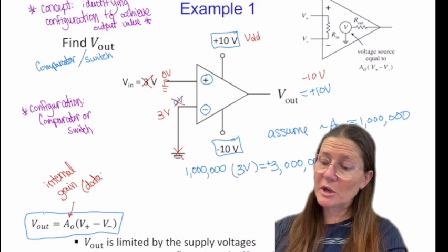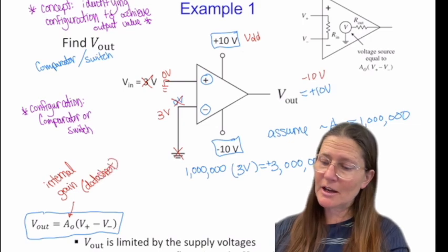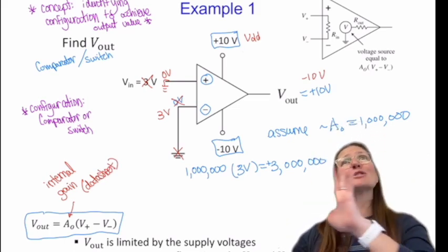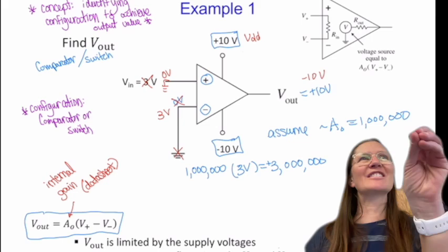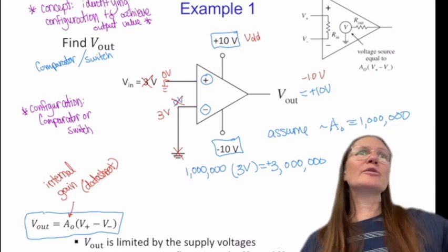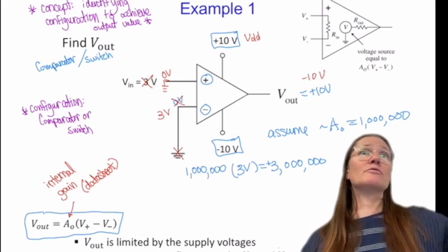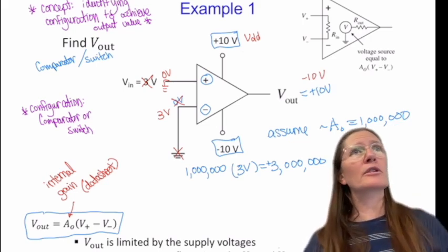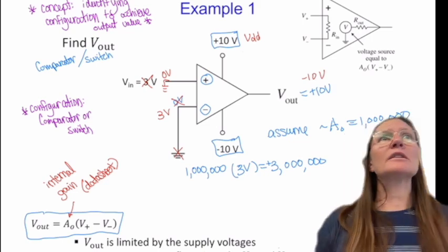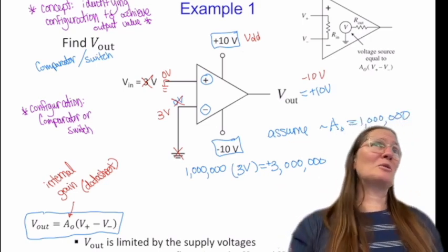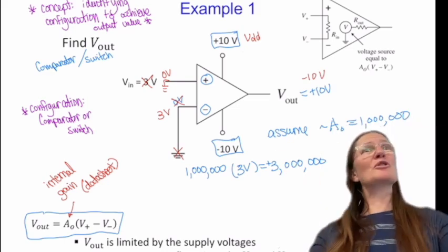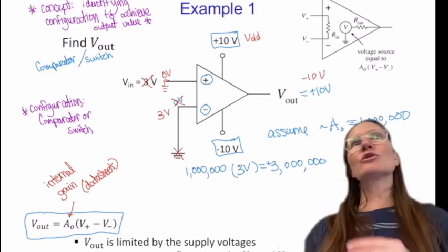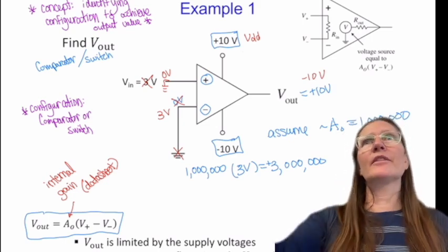It will be on a data sheet. And you need to learn what's called multiplots in 2280 to be able to read the data sheet to know what that value is. For us, we just need to know that it's large. So we're assuming it's large enough and that it's always going to act this way for a comparator. But as a designer, as you get more familiar with that, you're going to be concerned about what frequency range it actually needs to operate in. And those are the techniques you'll learn about in 2280.